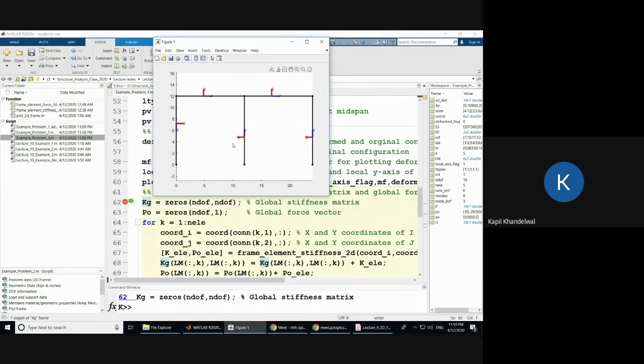When we are defining that load acting at the center for this member, we have to be careful. Okay, so we have to be careful because we have to first know what is the orientation of the member. So once you decide on the orientation of the member, you can define the other data accordingly. So the best way to think is first define whichever way you want to define the connectivity, and based on your connectivity, you have some orientation. And for that given orientation, you can define your loads. Okay, this is the way to think.